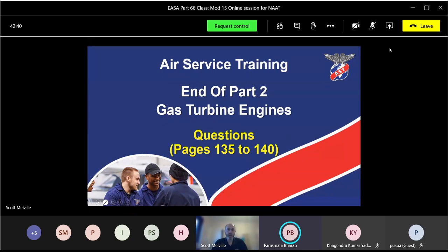Starts with C, ends in N. Carbon. Not titanium, unfortunately. Carbon is a good lubricant, so the valve can move back and forward. Remember, you've got high temperature in the air off-take, maybe 400 to 600 degrees. It's quite hot, so the carbon can take that heat and also self-lubricate, so it can move the slide valve back and forward.